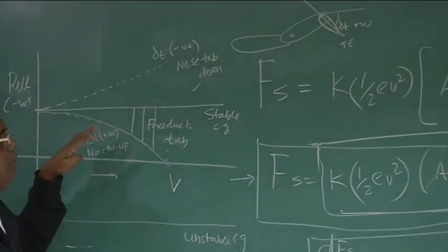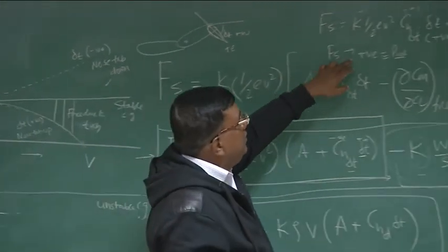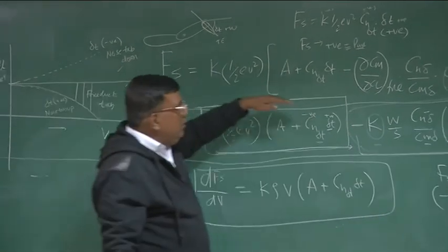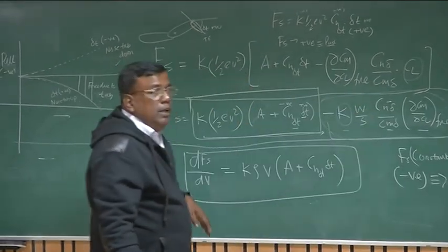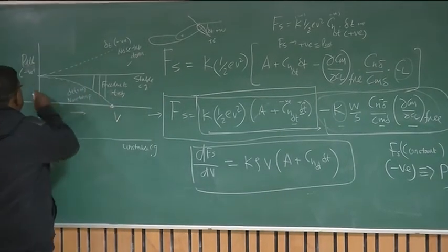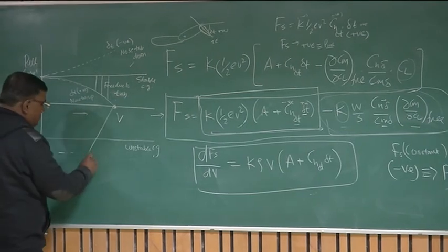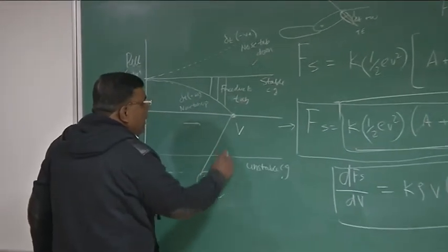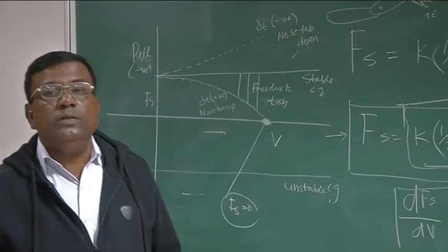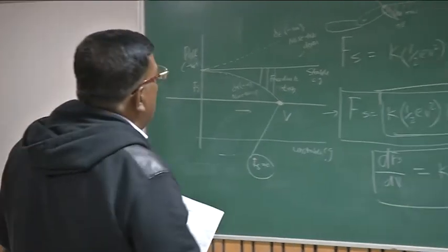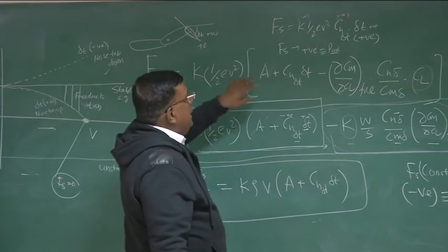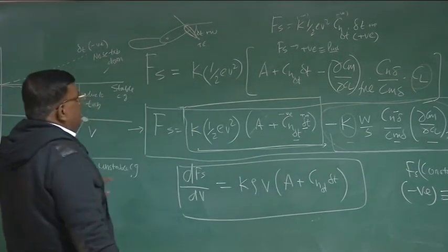You could see very clearly that if I put tab in this configuration, then that is giving a stick force Fs, which is positive, right? And this stability term was giving a negative force, which was like a pull force. So there will be a point where net Fs will become 0. So this is the point where you can ensure that Fs goes to 0 through tab. This is very clear. That is how I was telling you that you can bring equilibrium using a tab by proper tab setting, if you understand this.